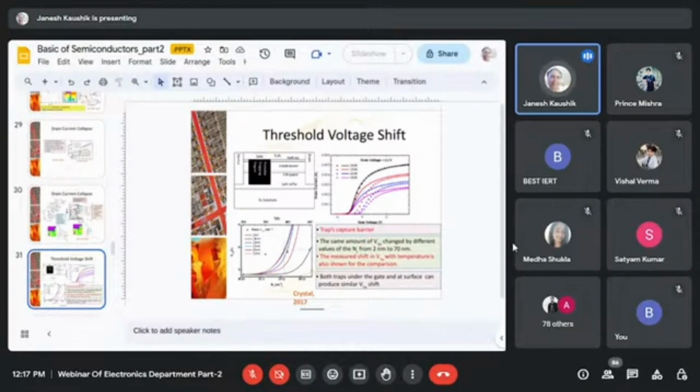So again, the role of surface states in the threshold voltage shift can be present, and that we have studied, and we have simulated this threshold voltage shift from both locations, at the AlGaN/GaN interface and the top surface at the silicon nitride/AlGaN interface. But then you can say, then sir, what is the benefit? What is the final conclusion? So that debate goes on.